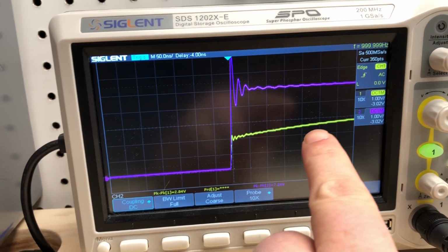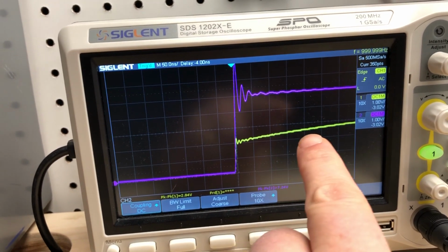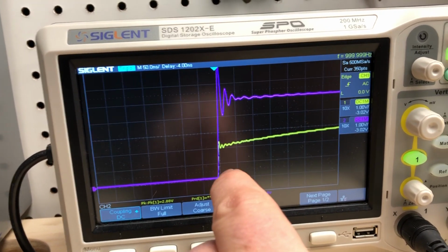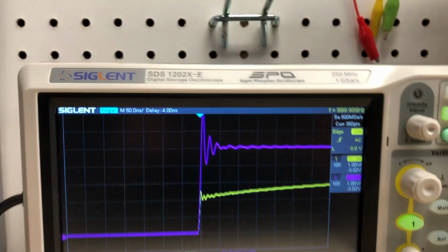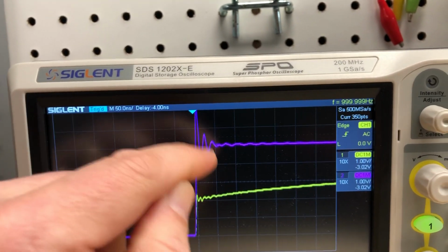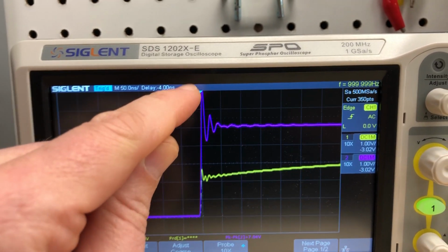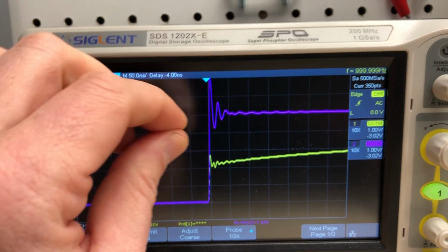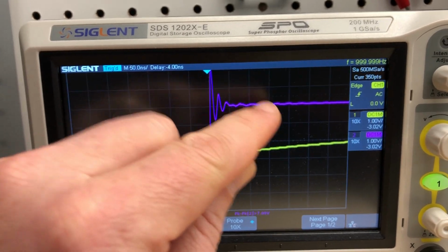So the yellow signal here is dominated by the exponential component. This is called the real component, the exponential component, because it's just a decay. That energy is just being dampened out by the system. It's probably being lost as heat in a transistor. And this ringing is called the imaginary component. That's because it is really due to inductance and reactance, which looks like resistance instantaneously, but that energy isn't being dissipated as heat. It's going into electric fields and magnetic fields that are then returning that energy to the system, which is why we get this bouncing.